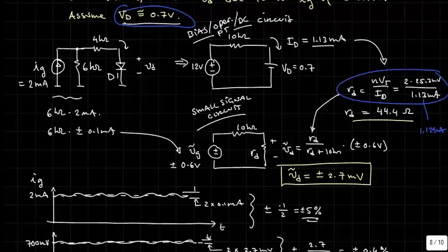Now, that depends on what you're driving your circuit with. In this case, because it's being driven by 12 volts, the current that flows is due to the voltage differential across this 10K. That voltage differential is the driving voltage, a large voltage of 12, minus the diode voltage, which is a small voltage. And so we can get away with just approximating VD, because if VD changes, say it's 0.65 or 0.75, that's only a change of 50 millivolts out of approximately 11.5 volts that are going to go across that 10K resistor. It will not produce a significant error.